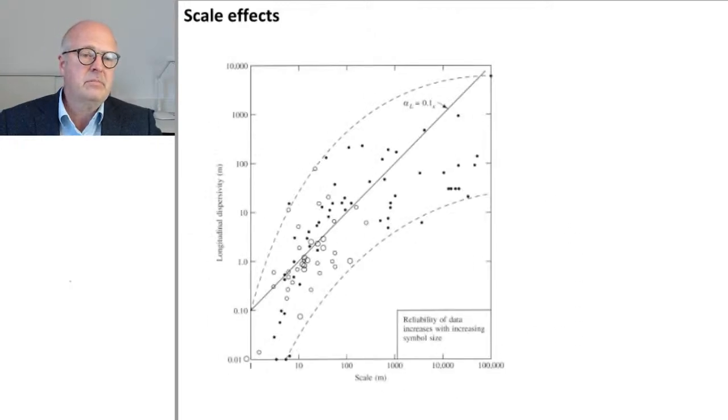Now, if you introduce a logarithmic scale and try to bring this to larger scales beyond 1,000 meters, to 10,000, 100,000 meters, then you might find, looking at the variability or the deviation, that there is a kind of lack of imagination of nature to invent new trouble, but you still find this line 0.1 times x. So remember this as a kind of simple estimator for dispersivity.